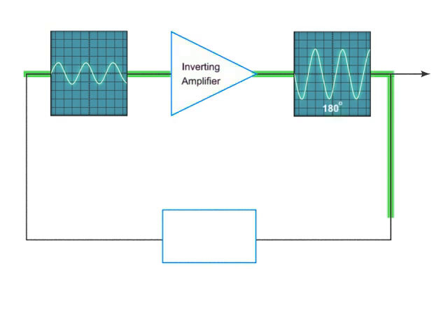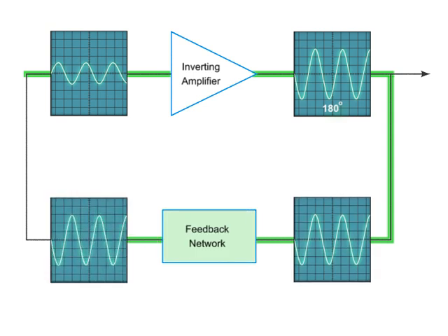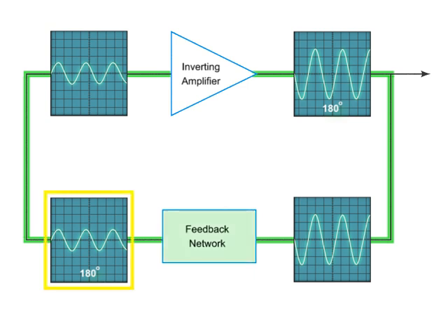The other aspect of an oscillator is a feedback network, which also has an inverting function, but as a result of passing through the network, the signal is attenuated. Therefore, the signal leaves the feedback network 180 degrees out of phase or inverted and reduced in magnitude. Also note that the output of the feedback network is now in phase with the original input of the inverting amplifier. Remember that the feedback network is frequency selective. Therefore, you only get one signal that will arrive back in phase.